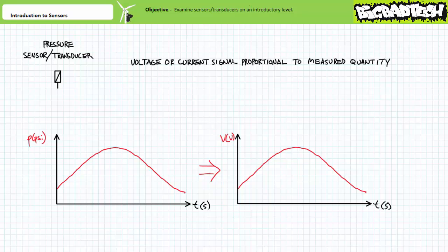A pressure sensor or transducer, in contrast, is a related input device that, rather than switching between two mutually exclusive states at a given set or reset value, produces a voltage or current value proportional to the quantity being measured, in this case, pressure. As pressure rises, the output signal proportionally rises. As pressure falls, the output signal proportionally falls. Sensors, unlike switches, not only detect a phenomenon, but also measure and quantify it. This continuously variant analog output can be used by an electrically controlled system to appropriately respond to a range of input conditions.